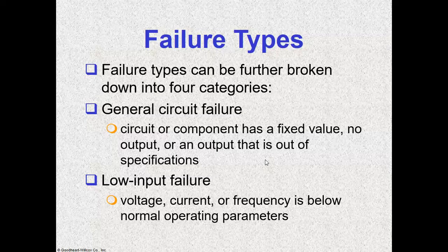So once you check your battery and that is good, you make sure that the alternator is charging properly and that you have no corrosion in the wires or anything like that, or the sensor connector itself. Or probably the trigger wheel, so whatever the sensor is getting its reading from, probably that can alter the range, meaning the air gap between the sensor and the component that it is reading is too wide.